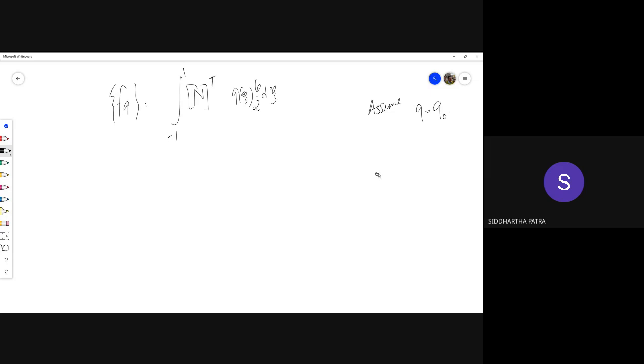And also if we assume a 3-noded quadratic shape function bar element, or the higher order bar element, that spans from 0 to L, the entire bar, then P times N transpose evaluated at L is P times N transpose evaluated at xi equals 1, which would again tell you it is simply 0, 0, P. So wherever you are applying P, could it be in the middle node, the left node or the right node, there you automatically put P.